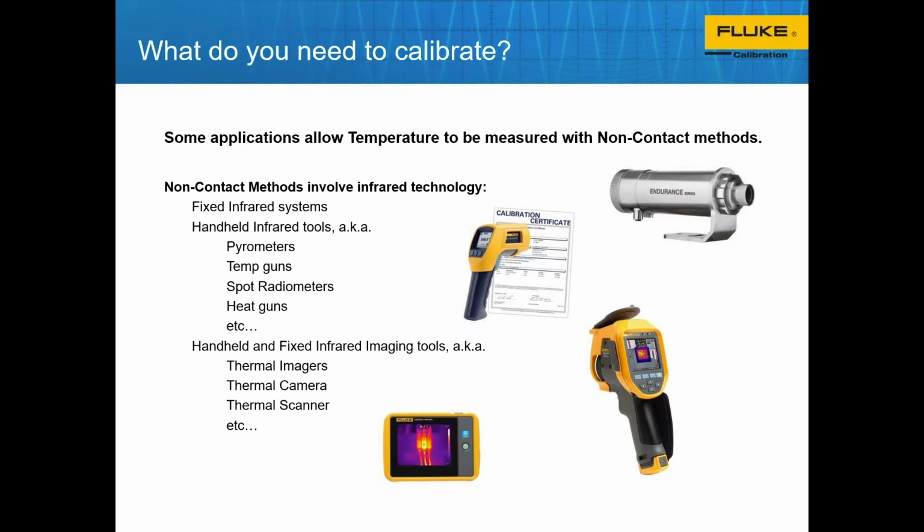And we're not actually measuring the temperature. Taking it a step further, we're measuring the infrared energy coming off of that surface. So there's a lot of assumptions that can happen with a temperature gun. That, combined with the fact that most temperature guns are typically plus or minus 2%, means they don't turn into calibration tools, although they may get misapplied or used as a reference. Some temp guns have a laser on them, and some people think the laser makes the temperature measurement, when in reality it's measuring infrared energy at a spot over a distance, and we call that the distance to spot ratio.